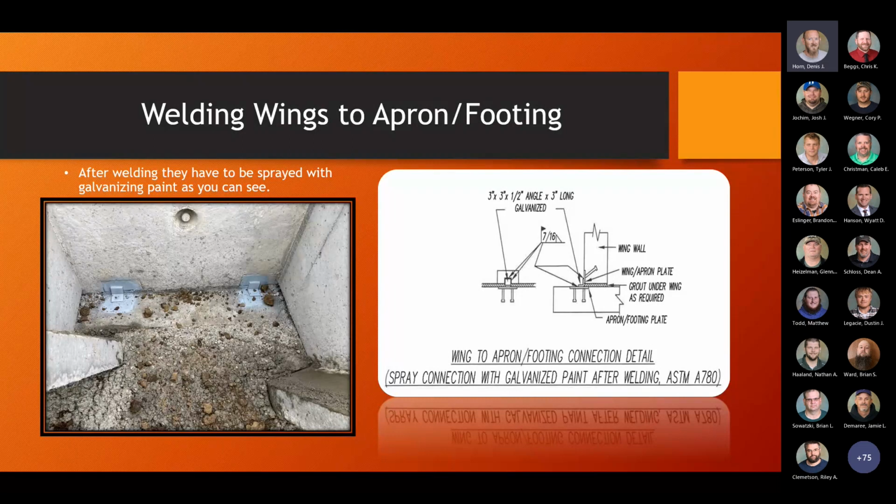All the brackets on the box need to be welded by a certified welder in galvanized field welds according to section 105.06D. Once the welding is complete and cooled, they then come around and cover all welded brackets with galvanized spray to seal everything from the elements according to section 854.